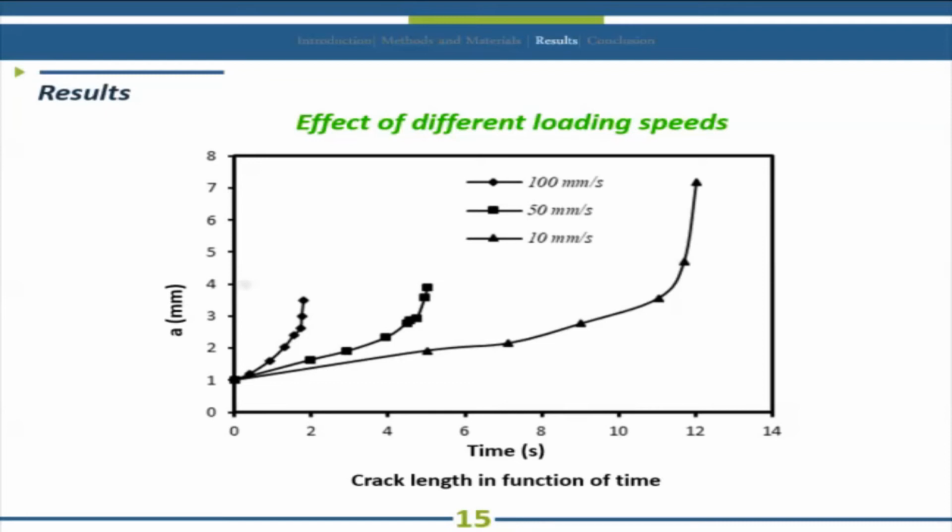Whereas a sample subjected to low loading speed does not break rapidly, it slowly deforms under the action of mechanical energy provided by the external stresses and the thermal energy due to the molecular motions. Fibrils act as energy absorbers. It can thus be concluded that the rate of loading is a parameter that controls and influences the behavior of amorphous polymers. Depending on the loading speed, the ABS adopts either a ductile or fragile behavior.